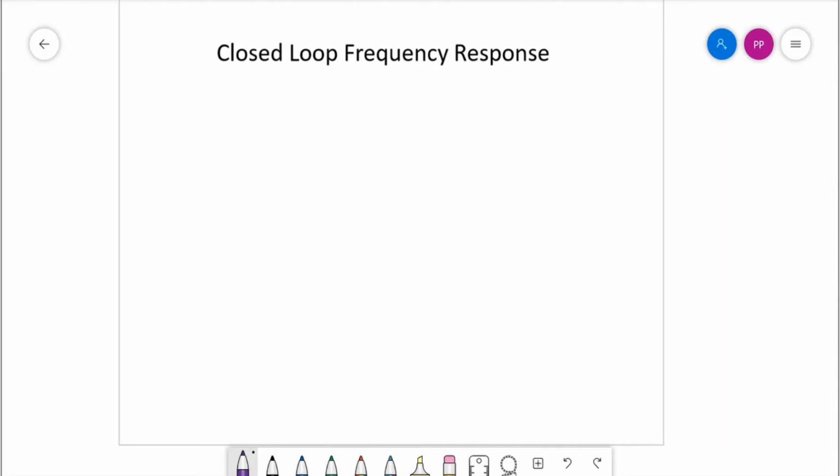So a closed loop negative feedback system is compensated by a controller or compensator to attenuate the most dominant root. Generally, the complex root pairs are creating the most dominant or most effective or most delayed response of the system. So we think of compensating the roots which are closer to the imaginary axis on the S plane.